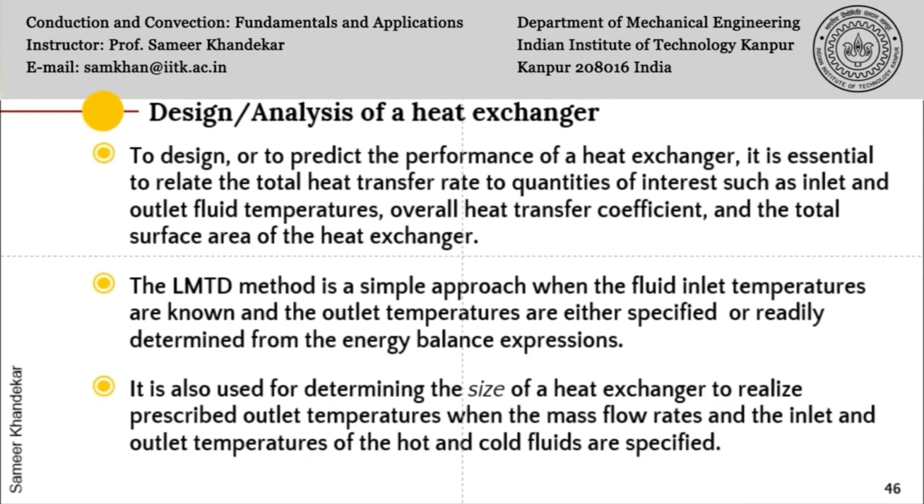So what do we mean by design or analysis of a heat exchanger? To design or to predict the performance of a heat exchanger, it is essential to relate the total heat transfer rate to quantities of interest such as inlet and outlet fluid temperatures, overall heat transfer coefficient, and the total surface area of the heat exchanger. When you do the sizing problem, you are actually predicting the surface area, what will be the total area required, or what will be the length of the tube required to attain a certain heat transfer.